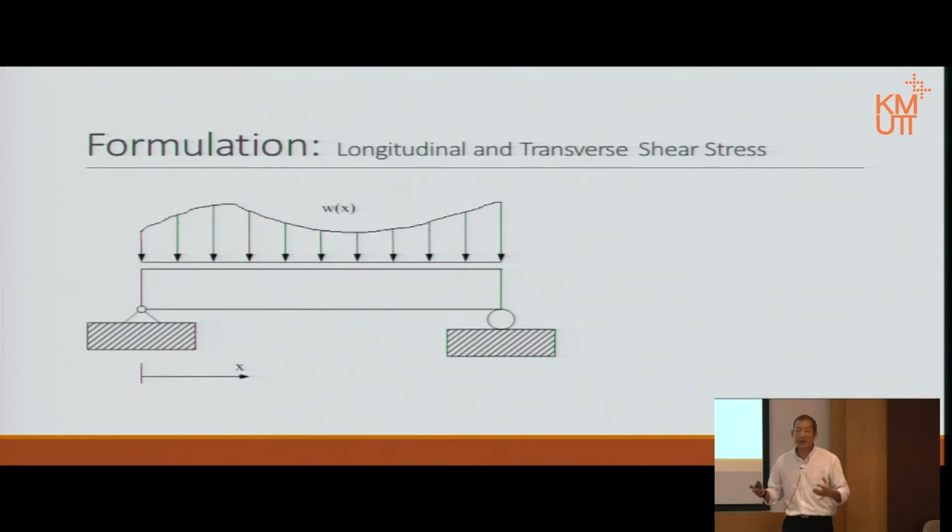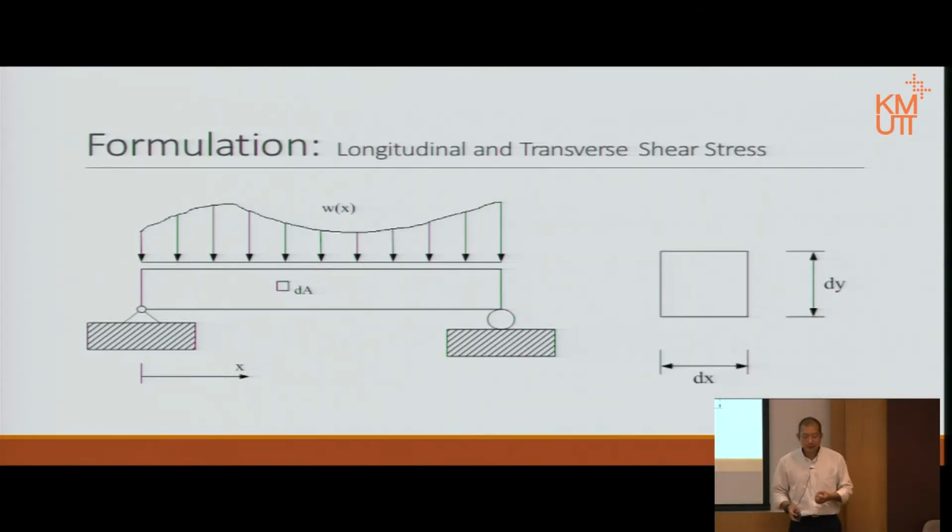Now, if we have a beam, any beam, subject to any kind of load, and we look at a small element inside that beam, that dA is the front view area, not the cross-section area. Okay? Let's look at that. The transverse shear stress that we usually look at is coming from the y-axis this way. Okay? Notice that this is actually a pair. Don't forget this element has the cross-section area on the side.